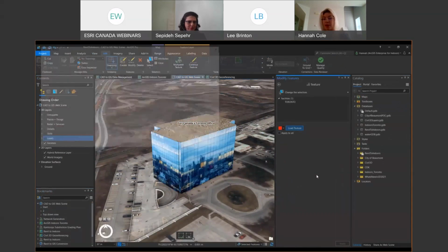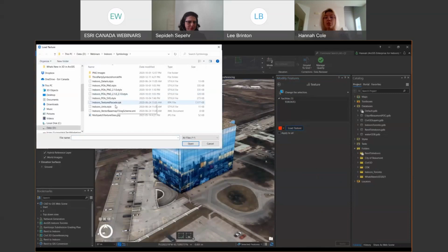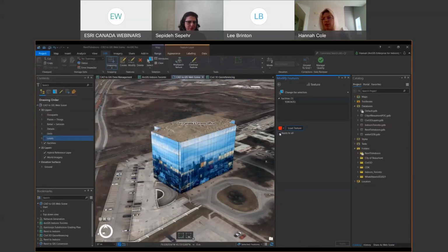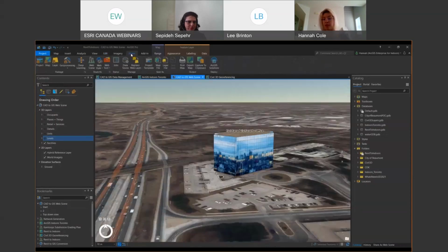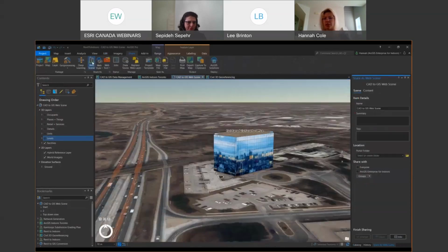Rule packages provided by Esri and textures obtained from image files can be applied to this multi-patch layer inside ArcGIS Pro to add that extra touch and really customize the look and feel of your 3D scenes. Once all needed map layers are compiled and layer symbology is defined, the 3D scene can be shared to your portal using ArcGIS Pro's share tools.